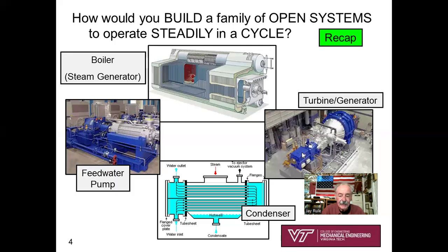Well, that's not the end of it, because we can't just spew all this low pressure steam into the atmosphere. We have to condense it so we can get it back into the boiler. Thus, underneath the steam turbine, you're going to find a condenser where we're rejecting heat from the low pressure steam, and that steam is condensed. On this picture, by gravity it falls out of the bottom of the vessel as saturated liquid, and it's going to flow into the boiler feed water pump. It pumps that liquid back up to high pressure, compressed liquid, and there you are back to your boiler.